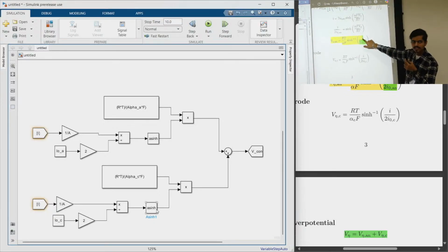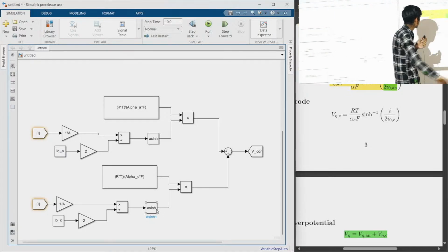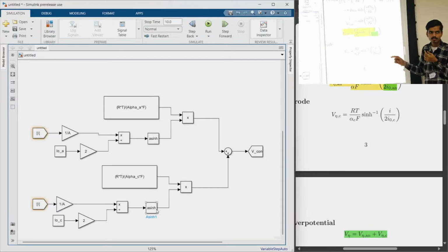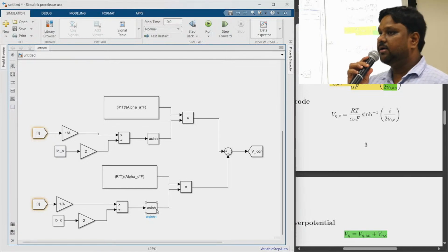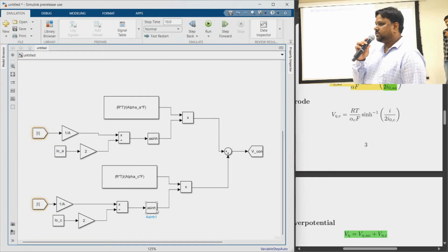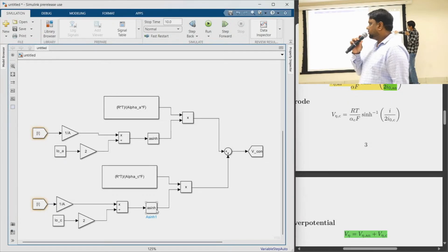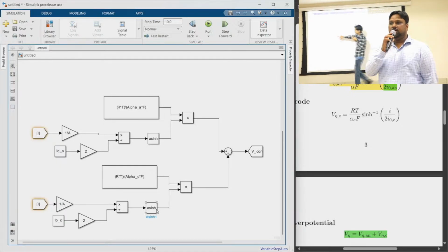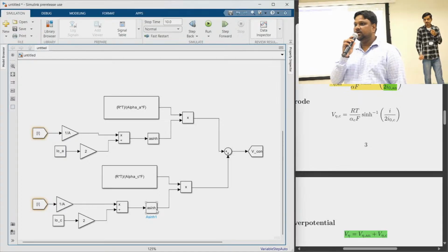This one. This is current. That's why we are dividing it by area to get the current density. Actually, we are getting current density here. This one is the current density. Small i is a confusion, I know, but that small i in the numerator is actually the current density, not current. That's why measured current divided by area becomes the small i. It is represented by small i in the literature also. Please note, generally in electrical engineering we assume small i is current, but in this equation we are representing current density.